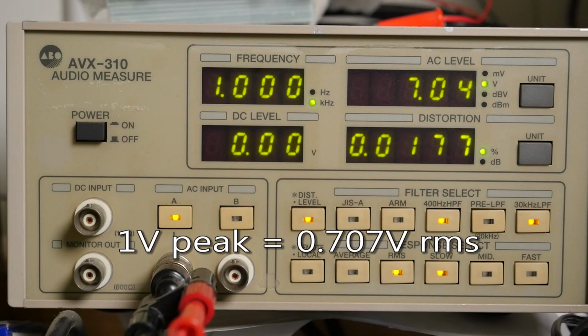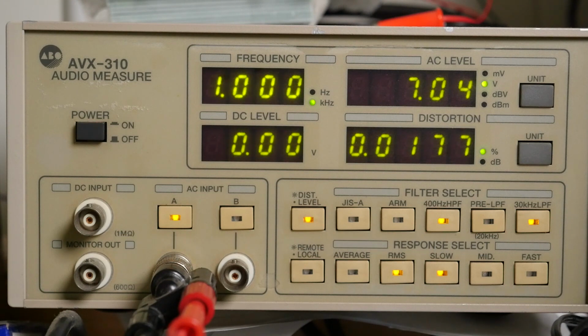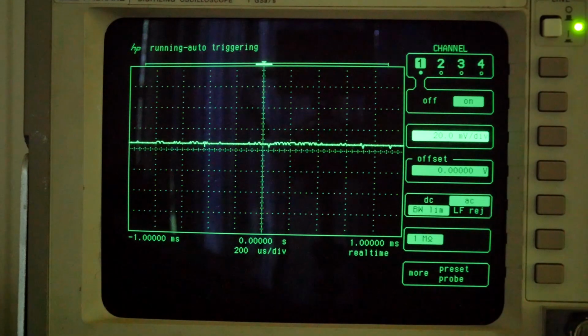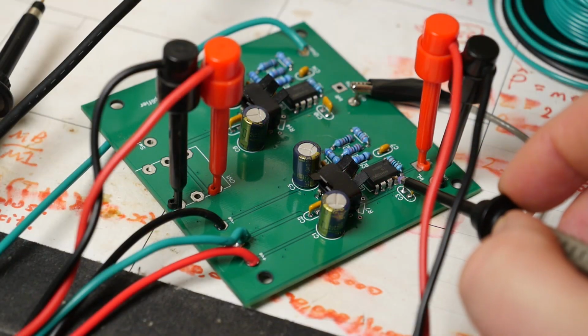fixed sine at 1 kilohertz, source level 1 volt. And we see from the analyzer on the output of the headphone amplifier that we're getting around about 7 volts RMS, which is around about right, and that our THD plus N number is nothing stellar, to be honest. That's fine because our source isn't particularly clean, and that's not really important. The main thing is just to check that we're not clipping, and that all looks good.